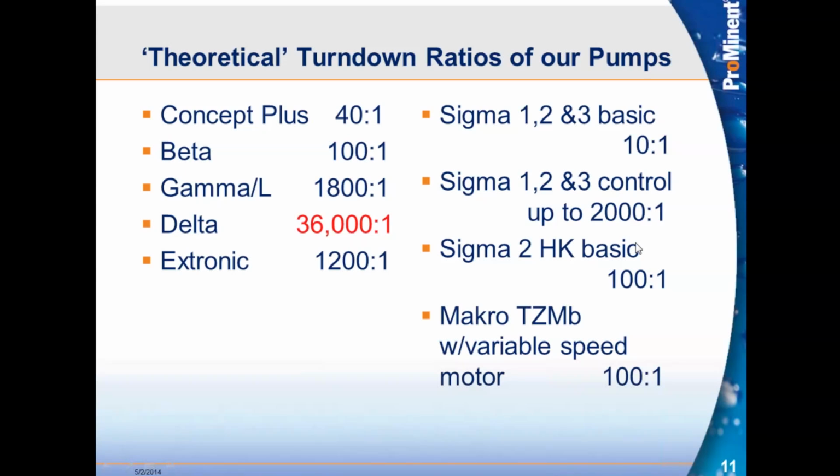So it's just a recommendation. Again, we know that there are applications out there that run well below that. We're saying 30% is probably where we should size it for. If you can run below that, it would be something that you have to test out in the field in your actual process.